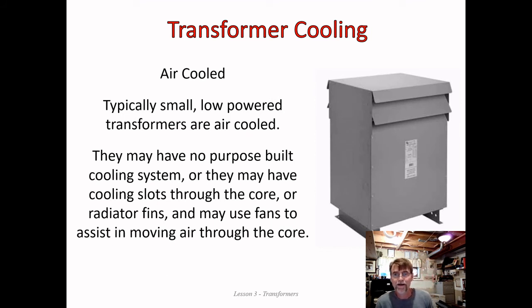So first of all, you have just simply air-cooled transformers. Typically these are small, low-power transformers, and we just use air to cool them. There may be no purposefully built-in cooling system, or they might have cooling slots through the core or radiator fins. So a radiator fin is simply a surface that does this.